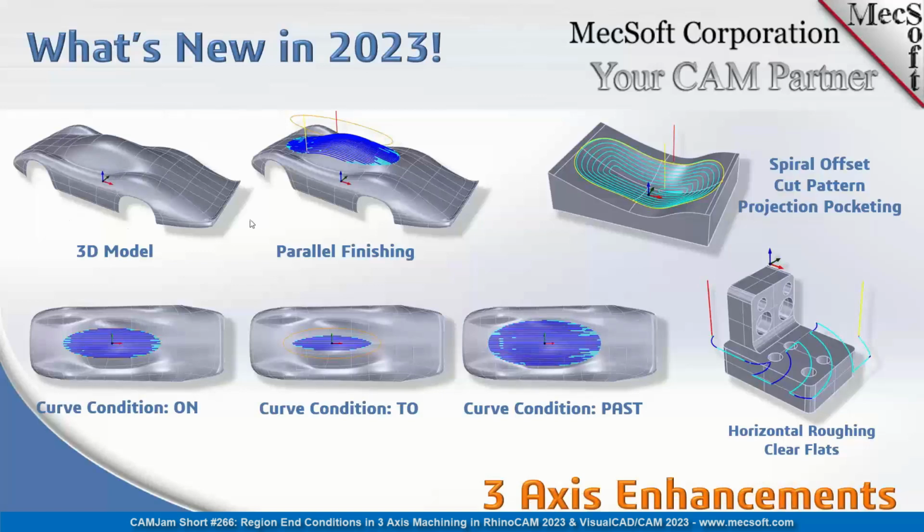And if you want to do some remachining in a certain area, you may not want to be limited to these ISO lines. So you can just draw the curve that you want to machine. And these are the different on, to, past conditions lined up here on the bottom.